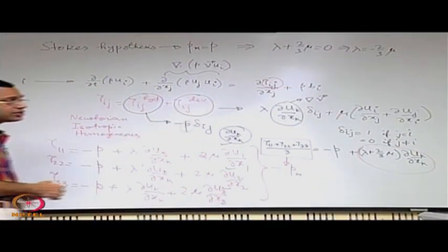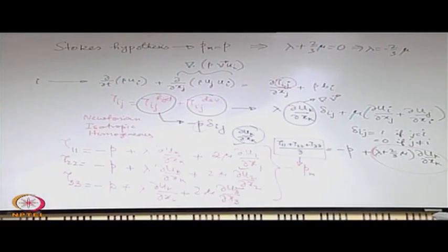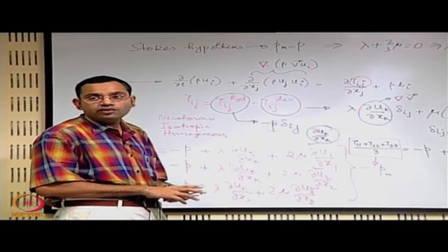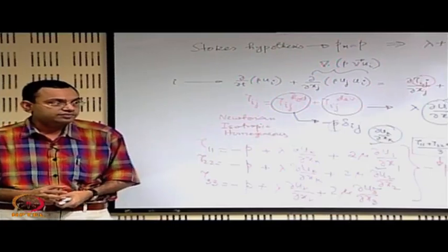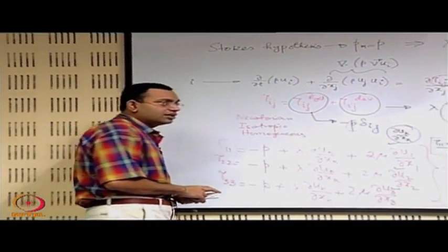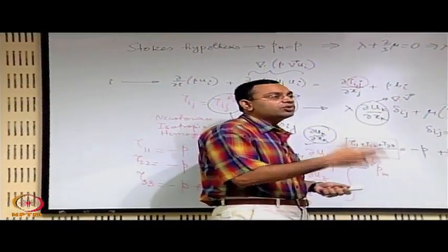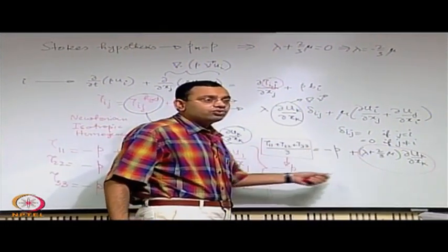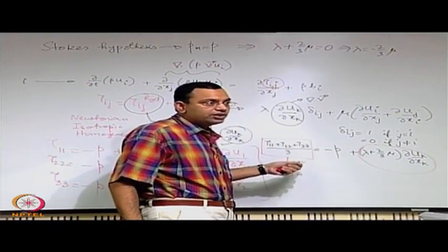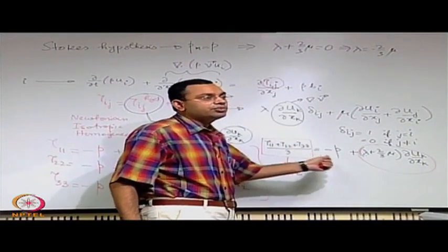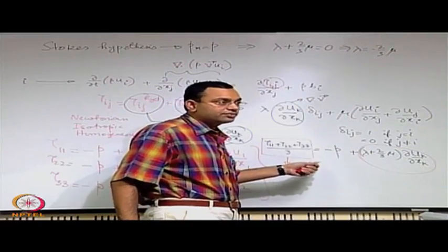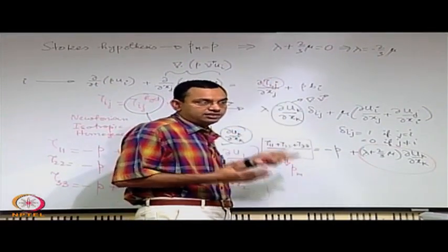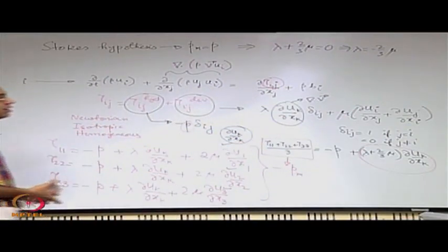But there are certain cases when you will not have a rotational and vibrational mode of energy, you have purely translational mode of energy. Think of a dilute monoatomic gas. So there you have a translational mode of energy, even when you look into it thermodynamically. So in that case you do not have any distinction between mechanical pressure and thermodynamic pressure, and then Stokes hypothesis is not a hypothesis, it is an exact reality, there is no deviation.